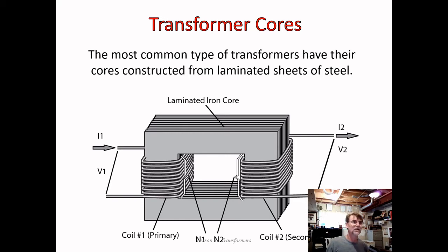Okay, eddy currents can be roughly defined as any unwanted current. Okay, this iron core, it will conduct electricity. So we have cutting action. We have lines of flux that are moving around, creating induced voltage. Okay, there's going to be induced voltage in the core itself, which is going to push current through the core itself. If it's a great big hunk of iron, you're going to have fairly large currents. But by laminating it, by cutting it into very thin slices, we really reduce that eddy current effect. And that's another loss that we're trying to minimize. Okay, I think the next slide gives us another picture to have more about conversation about this.